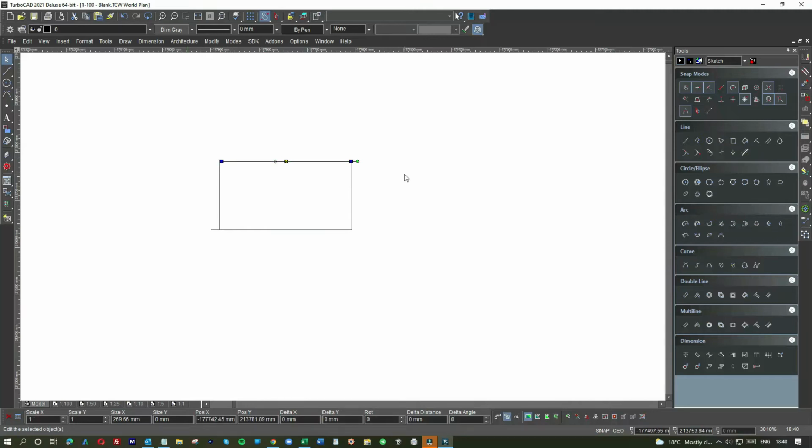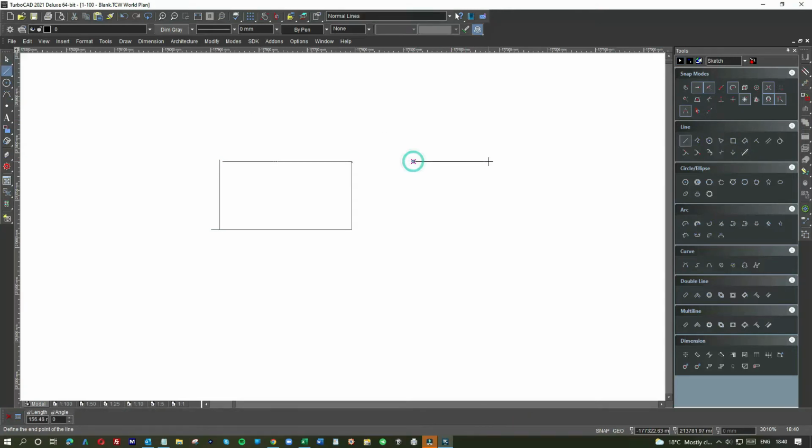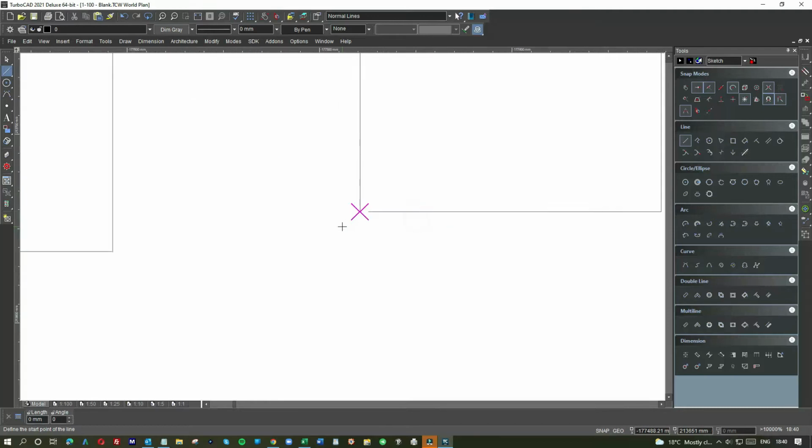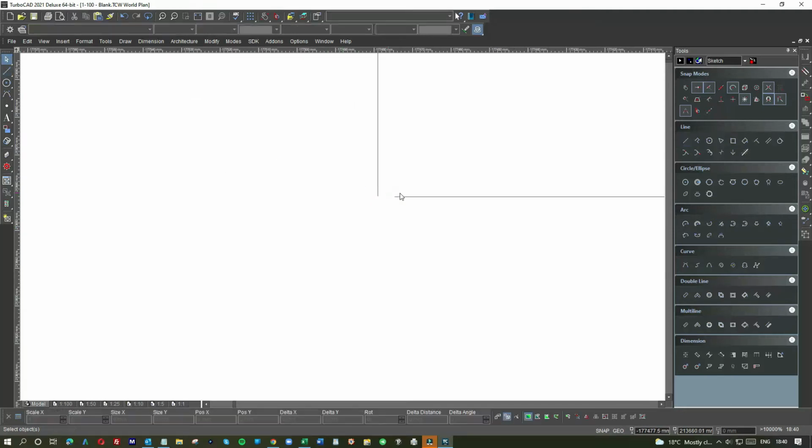Right, so let's leave that aside and start again, but this time we're going to turn on snaps, and I've got it adjusted to the way I want it. So now I'm going to draw a square again, or a rectangle. It's usually only the last one that I need to make a little adjustment on. And there you go. Now let's examine the joins, the corners. See, the corners are perfect. They're all knitted together. And that's what snap does.